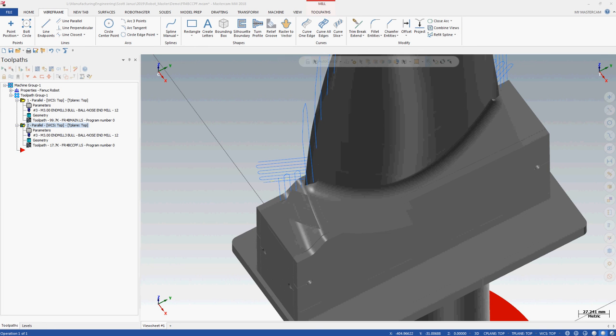Now, if I do it in Mastercam or if you're doing it using the Eureka software, it's not parametric, so you're gonna have to redo that whole surface. Here, I can just extend it and re-execute it. So what I'm doing here is trying to make this an even surface. So the spacing from here to here is 35 millimeters. If I'm using a 5 millimeter step over, it'll create a clean toolpath without a bunch of funky movements.